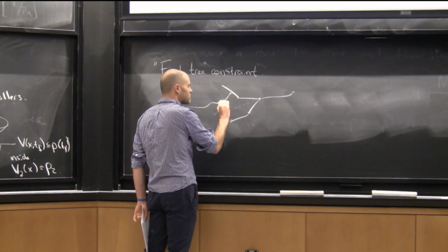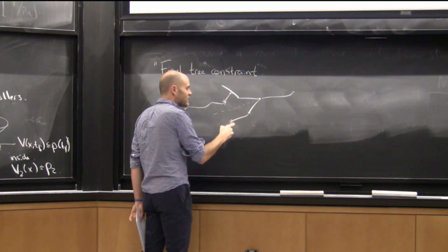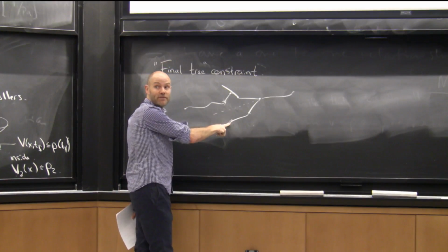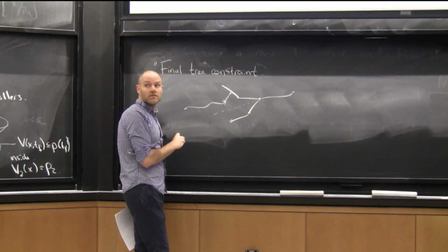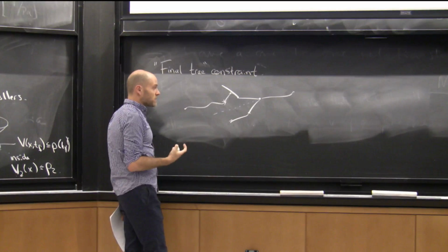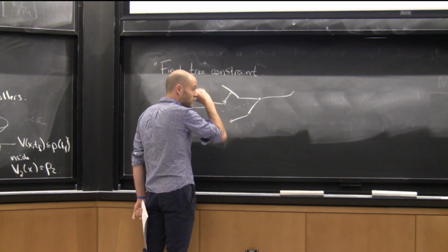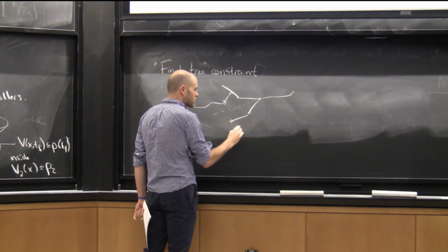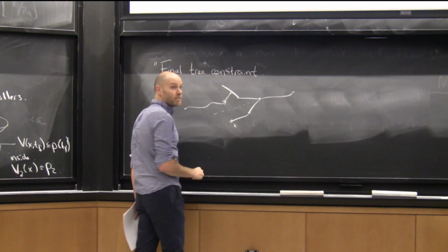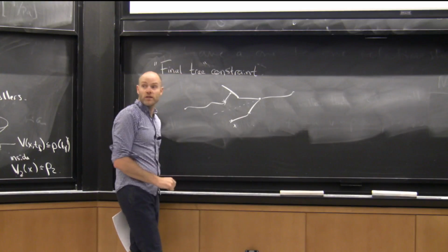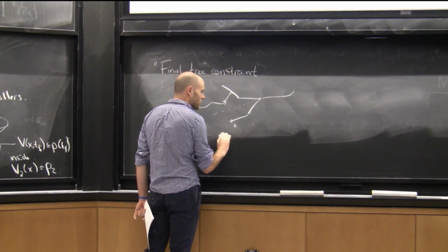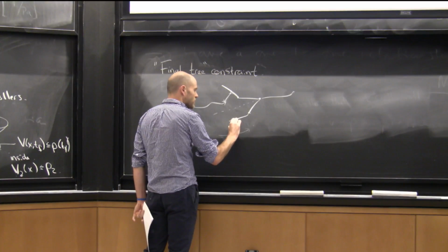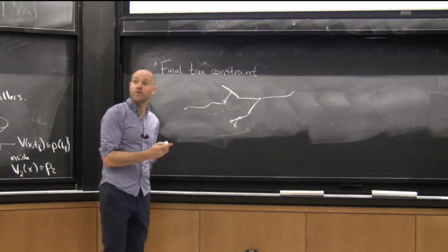But it has this property that even if your distance metric is not very good, the trajectory optimization has the ability to find a feasible connection to the tree. Yeah. And that turned out to be essential to make the algorithm work. So the problem we were talking about the other day of having a bad distance metric: if I say, here's my random sample, and here's the closest point, try to grow towards that, you can use that as an initial guess for your trajectory optimization. But if the dynamics have a flow in this direction, the trajectory optimization seeded like this will eventually connect somewhere that's feasible.